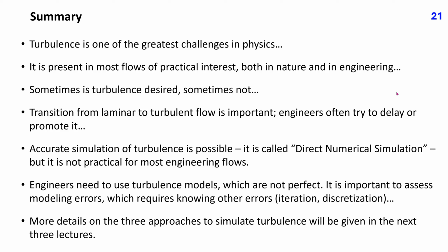However, although it is conceptually the simplest method for the simulation of turbulent flows, it is not practical for most engineering applications due to extreme requirements for computing resources, which increase over-proportionally with Reynolds number. Engineers therefore need to use turbulence models, which are not perfect and introduce modeling errors. It is important to assess these errors, which requires knowing other errors resulting from iterative solution and discretization approximations. More details on the three approaches to simulate turbulence will be given in the next three lectures.